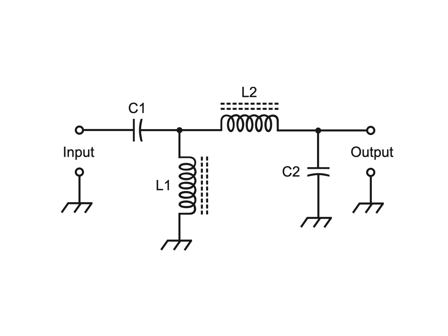This single miscreant component that costs a few pennies could, all by itself, bring down a sophisticated system. Breaking a massive system down into complex circuits makes it easier to determine which circuit might be creating the problem for the entire system. This complex circuit is then broken down into simple circuits, and a determination is made as to which simple circuit might be at fault. The simple circuit is further divided into separate components, which are examined individually for a possible fault.